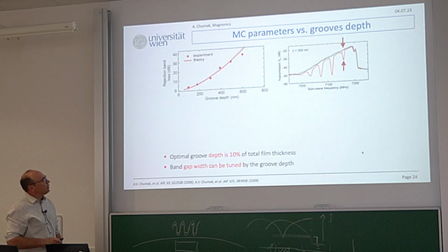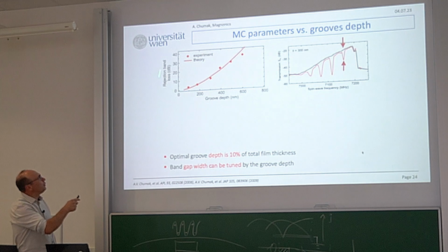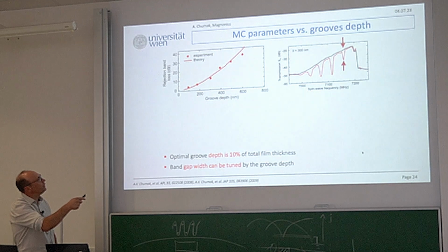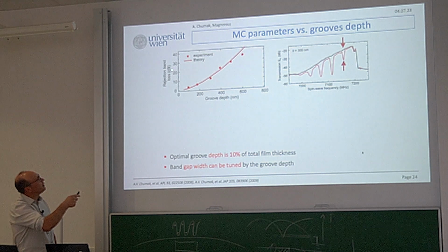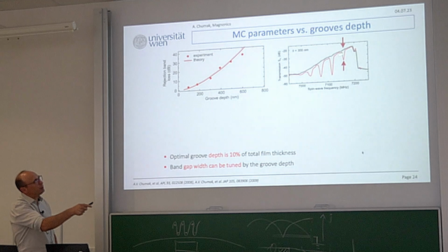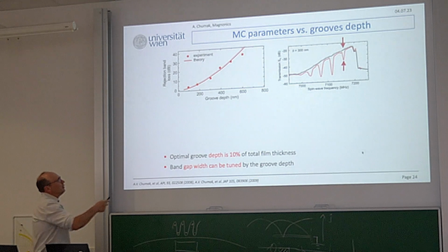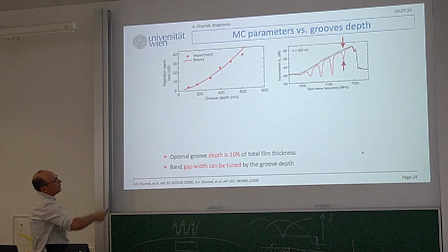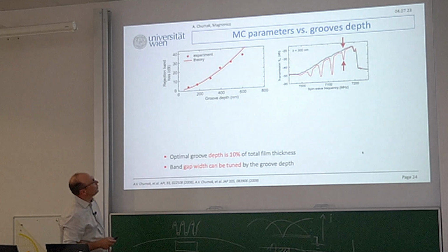Good, so that's so much about the magnonic crystal. If you plot the rejection band loss as a function of groove depth, you see such points. We could measure the rejection only for the first band, which is the smallest, because for the second and third the rejection efficiency was much higher. But even here we could reach 30 dB, which is 1,000 times, which is quite cool.